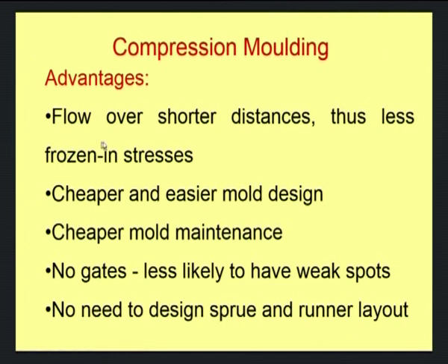So, this will ensure that the residual stresses, what we normally call frozen-in stresses, will be less. If a product has more frozen-in stresses, then that will decrease its tensile properties or mechanical properties. Wherever the product has these frozen-in stresses, when the material is subjected to a sudden impact at that particular point, the product may break. So, this is one of the principal advantages.